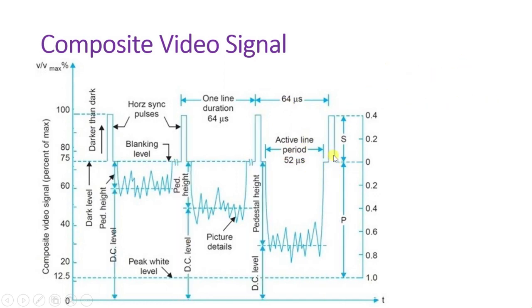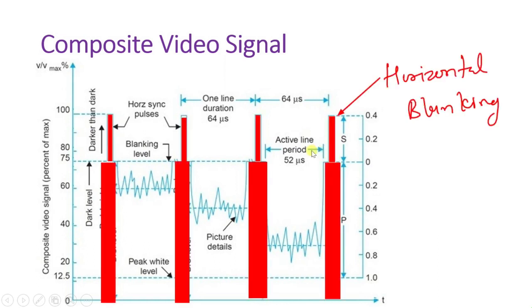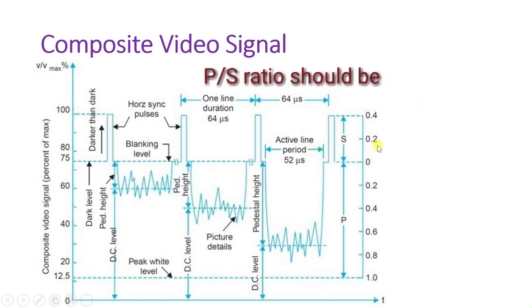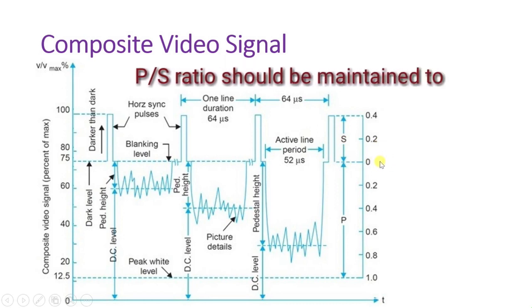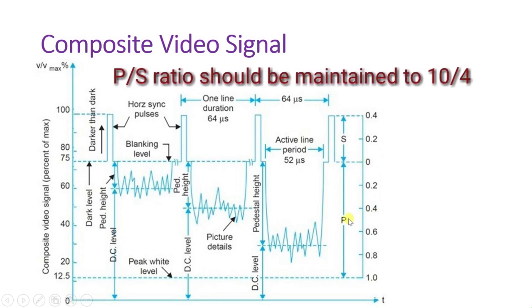Horizontal blanking time. Details of the horizontal blanking period are depicted in Figure 7.6. The interval marked H is the time required to trace one line, including tracing and retracing. Thus, the time for H is 1/15,750th of a second or 63.5 microseconds. The horizontal blanking pulse width is only 0.14 H to 0.18 H. Take an average of 16% as a typical value.